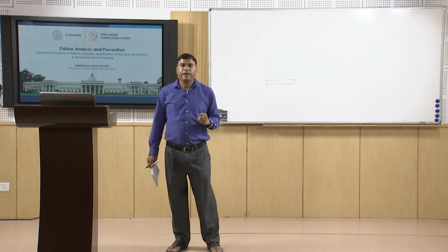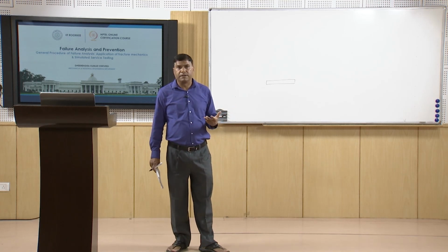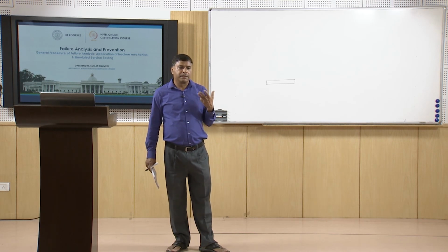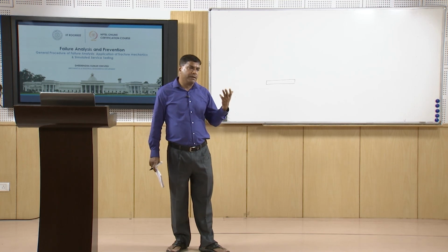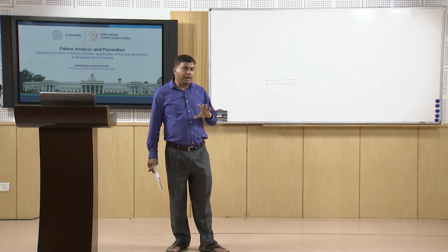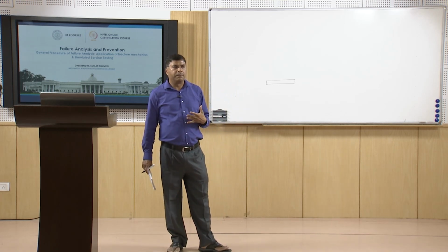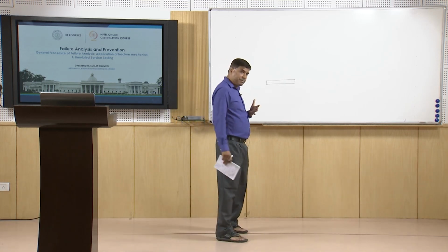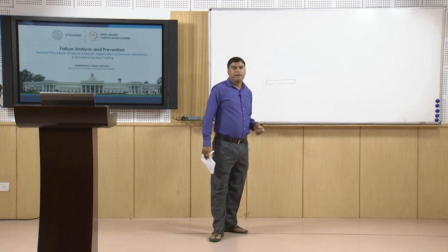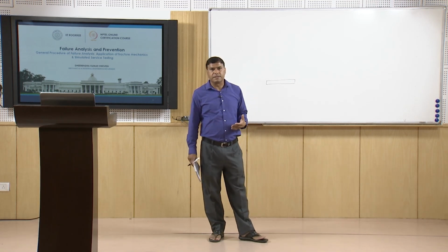Now I will summarize this presentation. In this presentation, I have talked about how to utilize the principles of fracture mechanics to analyze the case of failure with regard to the applied stresses and the size of the discontinuities present in the component. We can also determine the allowable size of the discontinuities or allowable stresses for given fracture toughness values of the material which has failed. So, this helps in determining the role of the discontinuities in the failure. At the same time, if you are not able to find properly in which way failure has taken place, then it would be a good idea to perform the test under simulated service conditions.